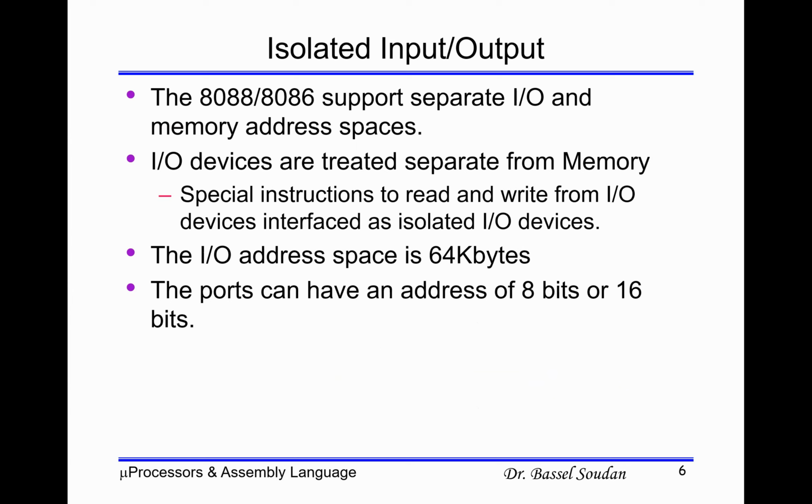So accordingly, for the x86, 8088 and 8086, we have a separate address space for the input output. So the address space for the memory is different from the address space for the input output ports. That means if I specify an address like this, how many bits here?